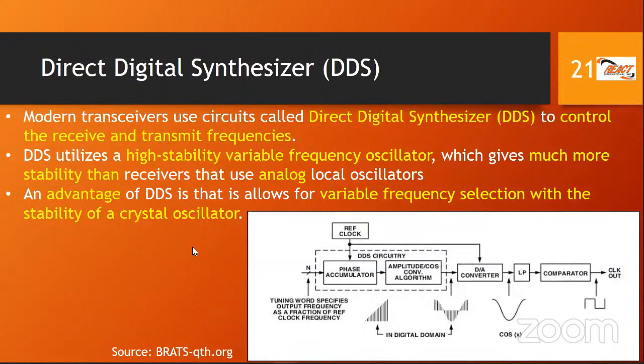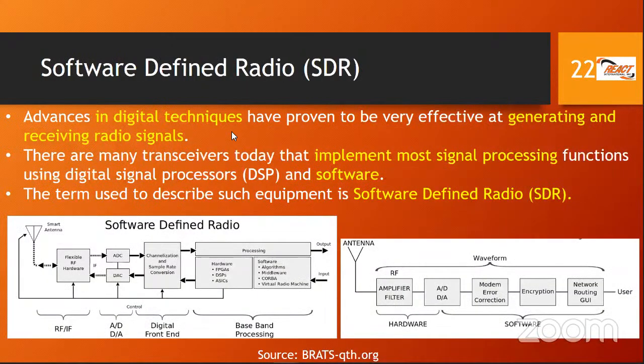And to modernize a little further, we now come to the concept of SDR, or software-defined radio. We have had a lot of advances in digital techniques over the years, and we have become very effective at generating and receiving radio signals using these digital techniques. So many transceivers on the market today implement most of the signal processing functions using DSP, digital signal processors, and software.